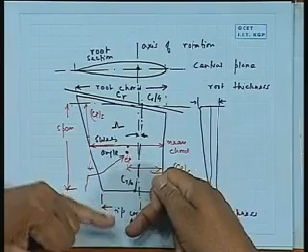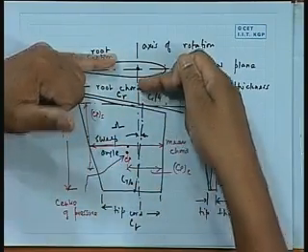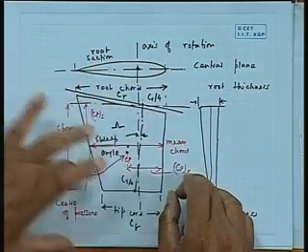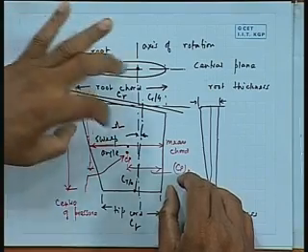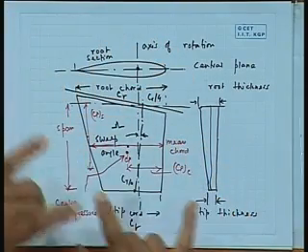Now you are doing this for a section. So if you want to do it for the entire rudder, then you have to do it for each section and add them up. You can integrate them along the span, and therefore you need to have some idea regarding the geometry of the rudder. What are the parameters that are basically used and based on which you normally do this rudder force estimation, etc. That is what I am trying to say.